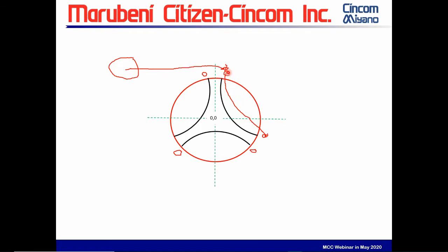Now, if you have a y-axis, most people would just go there and just program in the x, y with the radius. If you don't have that, this is what you would use. For instance, you have the back, and if you have on the back tools, you don't have a y-axis machine, you have a type 8. You would have to do it with this methodology of G12.1. It gets problematic sometimes when you go below center on a y-axis machine that doesn't drop far enough on some tools. This is another way around it.